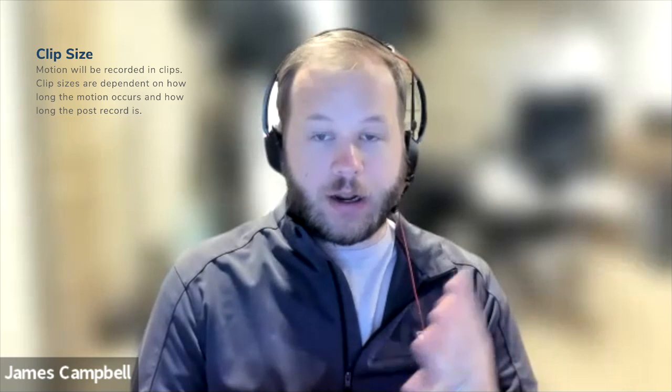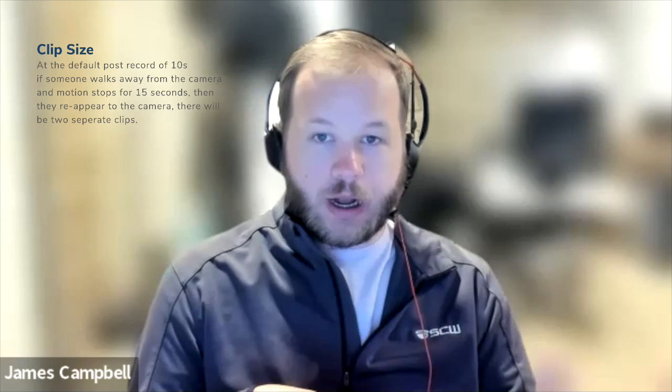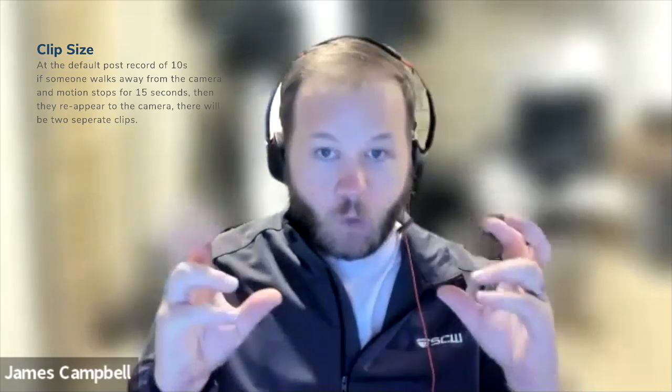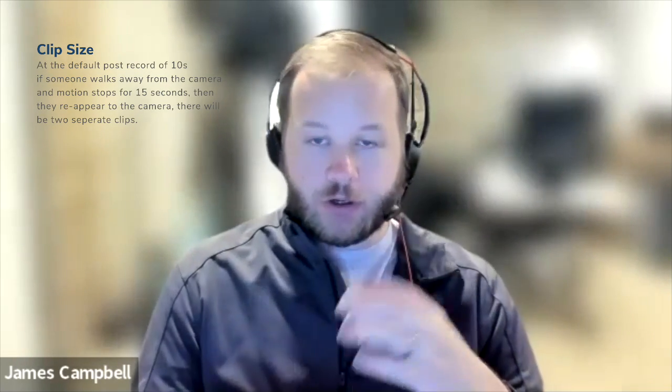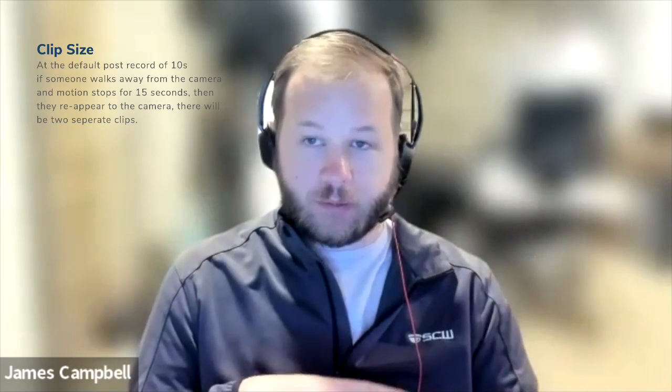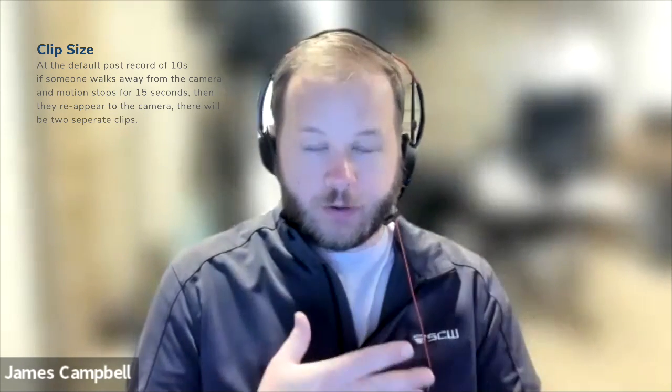If he goes back in there 5 seconds later, that's going to be a brand new clip. So it's going to create multiple clips for that one incident, I should say. Now, if they're constantly on that camera and it's constantly detecting motion, let's say that person's in front of this camera for 5 minutes, then you're going to get one 5-minute clip out of that. Of course, you can clip in segments if you want to, but if you are pulling a full clip and they keep going in and out of the camera, you may end up getting multiple clips out of that. So sometimes increasing the post record can help in that situation, to take it from a different perspective.